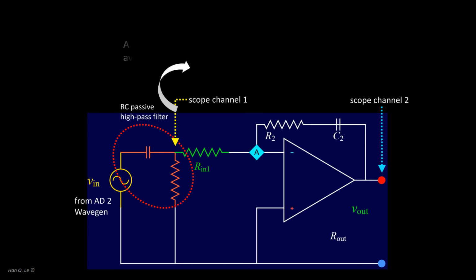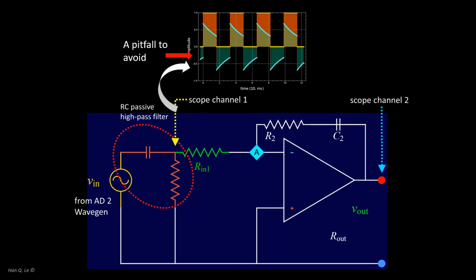If you see a waveform that substantially deviates from the square waveform as shown, it means the RC time constant is not large enough at the frequency studied. Given that input shape, the output will not be a triangle waveform as expected.